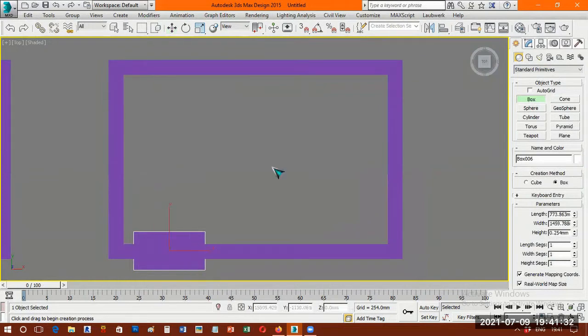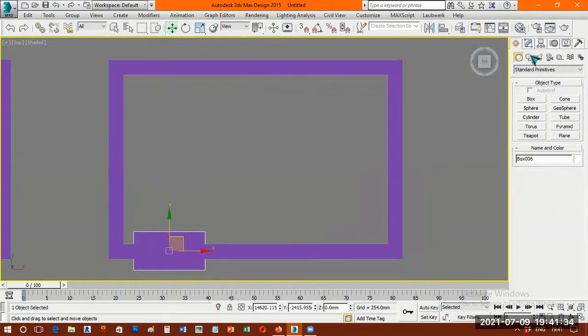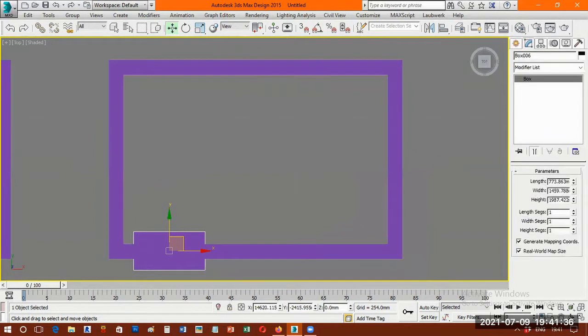Raise height, again right click mouse, over. Means I go to modify, the width, the length is, doesn't matter. Let it be 1000 mm, doesn't matter. The width is 1200 mm. Door width, I'm setting this to 1200. Door height, I'm setting to 2100 mm.